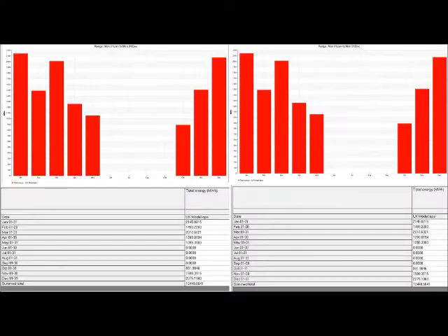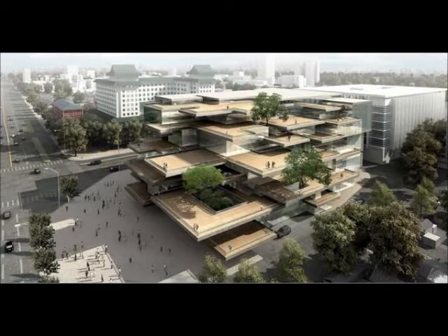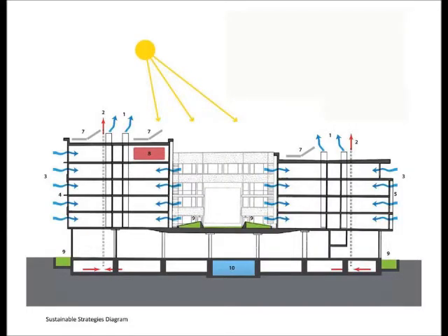As a conclusion, the research proves that building orientation would definitely impact annual energy consumption, as it impacts the building envelope solar gain, which adds to the required energy to reach indoor comfort level. Therefore, it is recommended to test and examine different orientations for buildings in order to comply with each site's requirements. On the other hand, it was concluded that adding a shaded courtyard will impact the indoor environment and natural air velocity at the interior spaces, especially when responding to wind direction and selecting courtyard location.